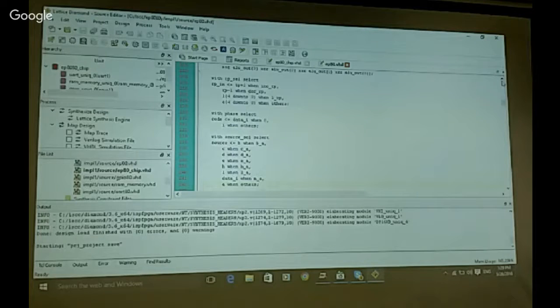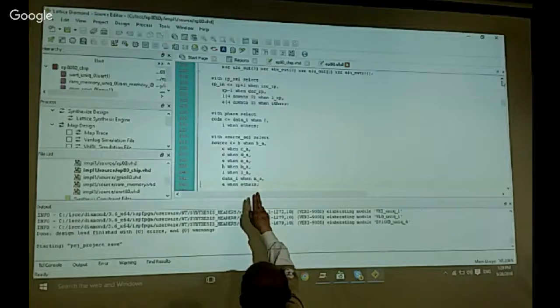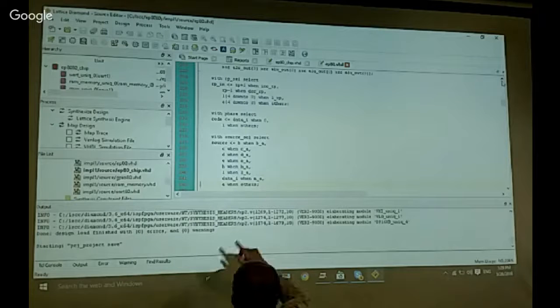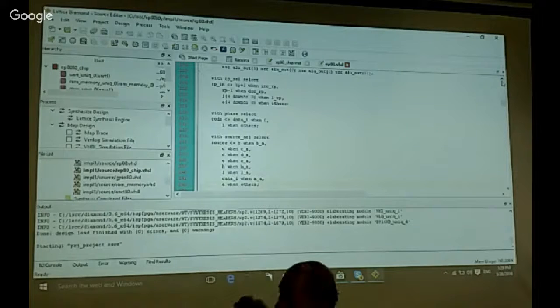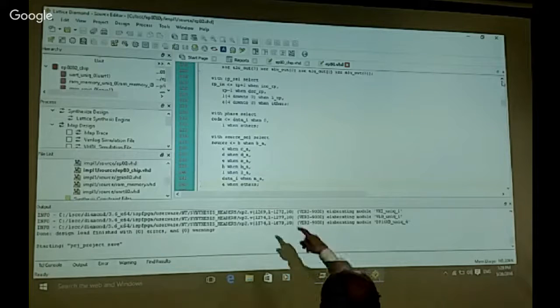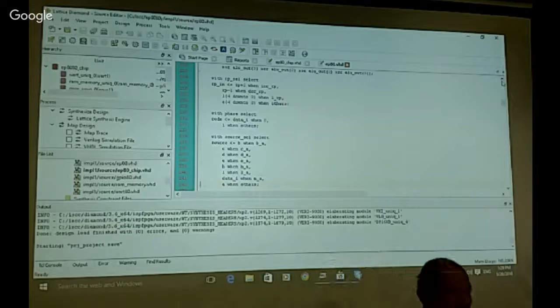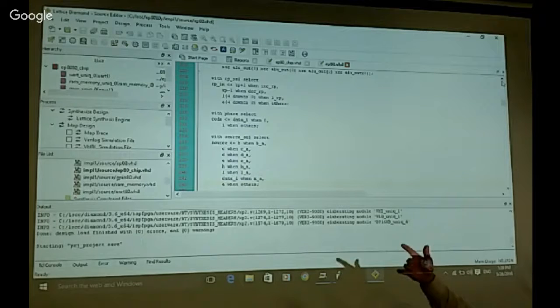This source, I think, goes into one of the ALU inputs, and this source selects one of the 8 registers A, B, C, D, H, L, and P as input. Okay, and so this one goes into the ALU as part of the ALU select. Okay, so these are all the multiplexers.